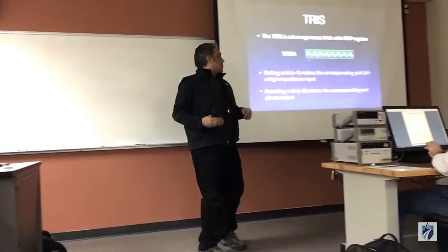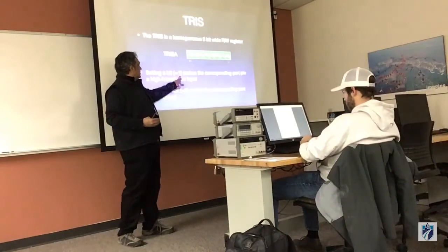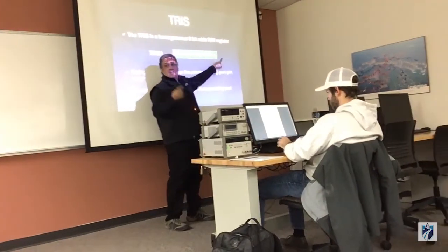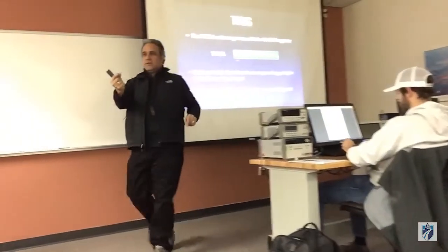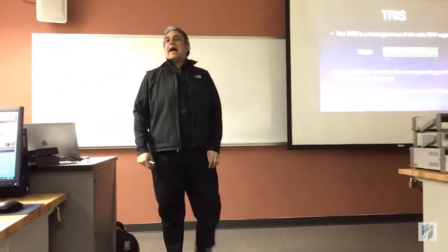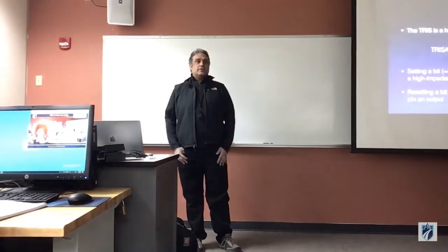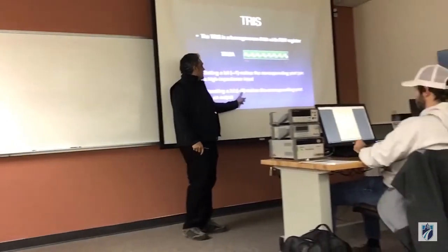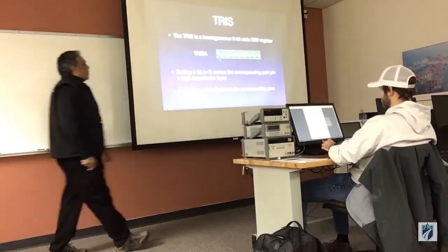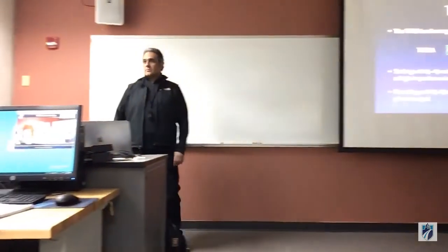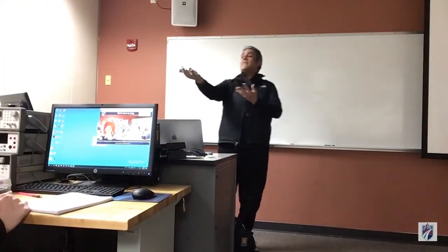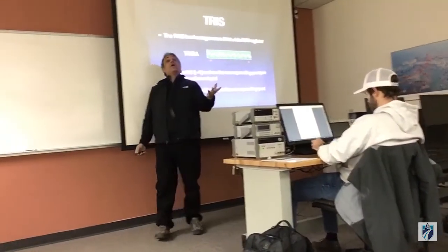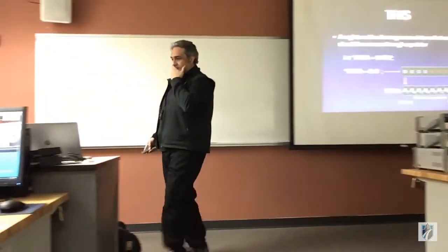What this means is that microprocessors, when they go into input, in this particular case by taking the tri-state circuit and depositing a 1 in the location that I want to make an input, that is going to make that pin a high impedance input. Does that make sense? All right. If you put a 0 in its place, you're going to make the corresponding port pin an output. All right? So it is your choice. You have the ability to actually manipulate each and every one of those circuits one at a time. Okay? So it looks like this.